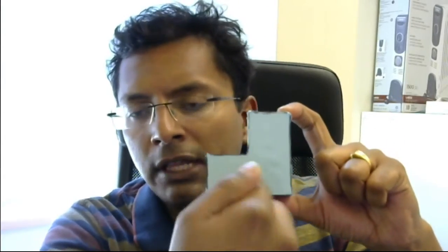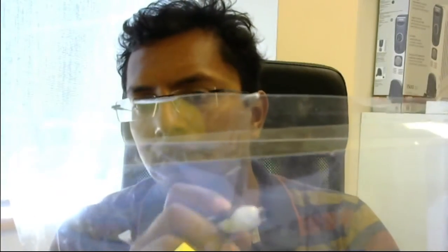The other way to do it is you can think of actually viewing this object and then putting the screen in front over here. So think of having a transparent or a translucent sheet. If I have a transparent sheet like so, and then I have this object, think of this actually getting projected to the front of the screen, and then I create some scribbles over here. You can see a scribble over here. This would be how the object looks. So that's getting projected to the front of the screen. These are two ways in which you can do this projection, and this is where the two standards differ.